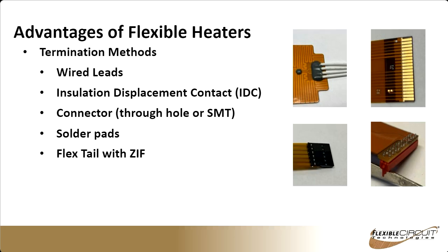We can just open up pads and ENIG plate them for you, or pre-solder them, and then you can solder wires of your own. Or another common one is the flex tail with a ZIF pattern. I think about 80 or 90% of the designs I see nowadays have ZIFs, especially with flex circuits.